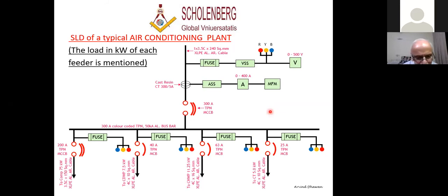Now, you have construction taking place, right? You're an AC guy. Now, piping drawing, that you know what to do. You know the symbols of the piping. Because if you're executing a project, it is executed based on what? Based on drawings at site. You get concept drawings first, then you get fit for construction drawings, right? Then after construction, you get as-built drawings. So three sets of drawings are there.